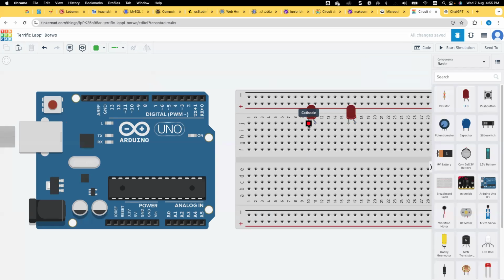And since in this internal section the pins of the breadboard are connected vertically, as you can see, and here they are connected horizontally, I can take my ground from here and connect it here. So now all this row is connected to the ground. So I can take a wire from here till here, a wire from here till here, and then half of the circuit is done. It needs to be continued.